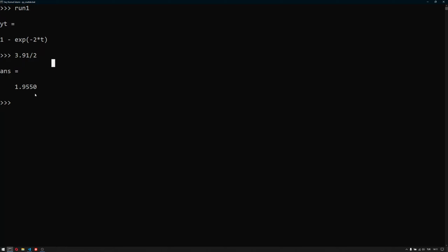And you get the idea. The basic formulation here is therefore 3.91 divided by the pole, because we have just a first order system. It has 1 pole only, and it depends on this. The generic solution would be p times t, and I would be always looking for 3.91. Therefore, t should be equal to 3.91 divided by p. So that's it. For first order system, this is quite obvious.